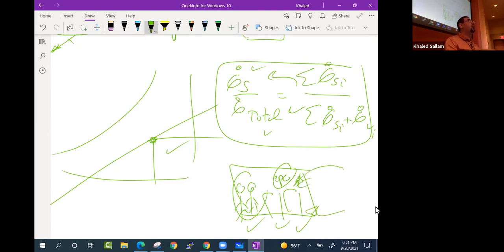To be able to figure out that building would require this much Q dot S, this much Q dot L. And then they will design the system. Once you have those loads, then you move to the next step and you start designing the architecture of the machine itself. Okay, so to answer your question, how did we come up with those things? Load calculation based on tables and based on the building, the nature of the wall, right? I mean, it's amazing how much time they actually spent on just load calculation.